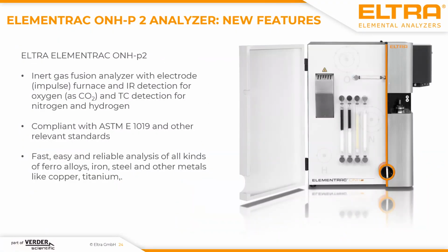The Elementrac ONHP2 is an inert gas fusion analyzer which is compliant with all relevant international standards, for example ASTM E1019. It uses an electrode furnace for fusion of the sample, and the released gases are measured in an IR cell or in a TCD. It's not only suitable for the analysis of ferroalloys, but it can also be used for the analysis of steel,